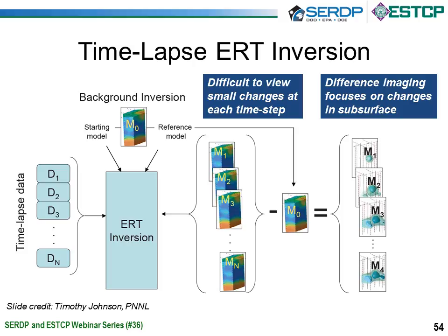So as Lee mentioned, we can also use geophysical technologies, and in particular ERT is very well suited for monitoring applications. So we can change something in the subsurface, like inject an amendment, and we can then take data at each different time step. So what we end up with is a bunch of static images, which are dependent upon, again, lithology, water content, porosity, temperature.